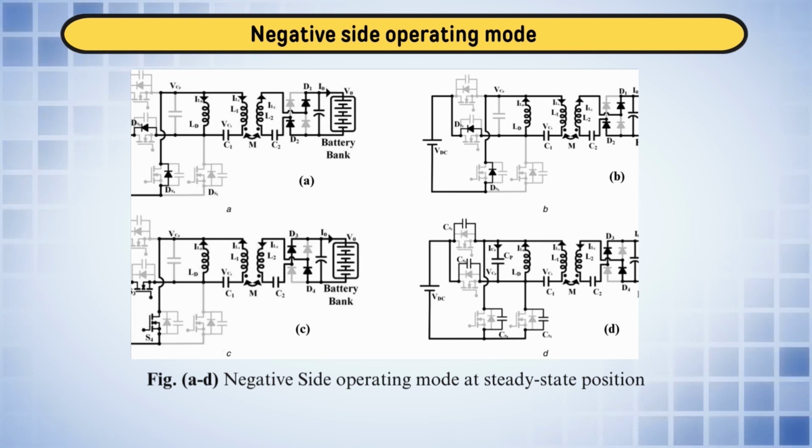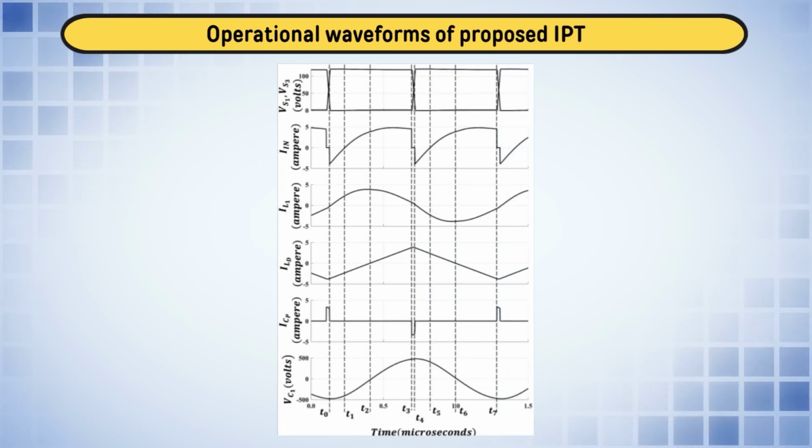The primary side's 3-leg minimizes the voltage stress, while the secondary side's high current provides fast charging. Hence, this configuration is prominent for low voltage fast EV charging applications, especially in case of domestic or home based charging. So, this is the Scott connection based dual active bridge converter. You can see at the secondary side, toward the battery side, we have 3 legs, however, on the primary side we have used only 2 legs.